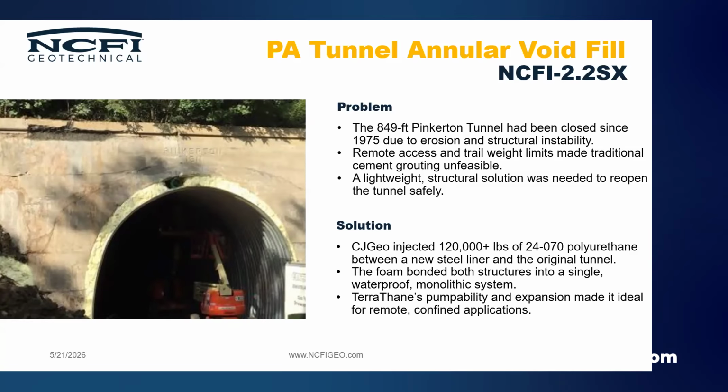When you're doing this type of job, it's easy to monitor to make sure you're getting complete fill, because you can use thermal imaging to make sure that you're getting to all the areas when you're working with a steel liner like that. It doesn't always work when it's a concrete liner or when you're dealing with concrete, but it works really well when you're dealing with metal.